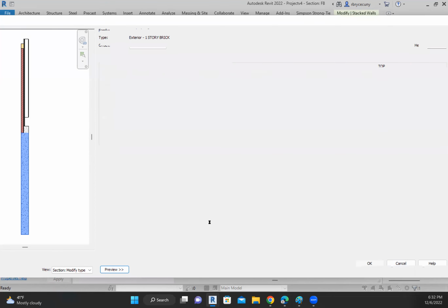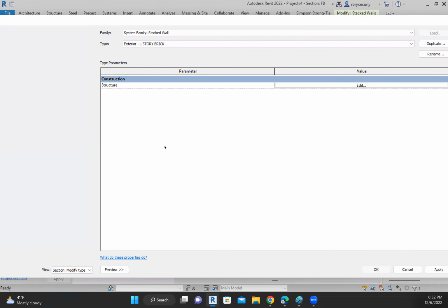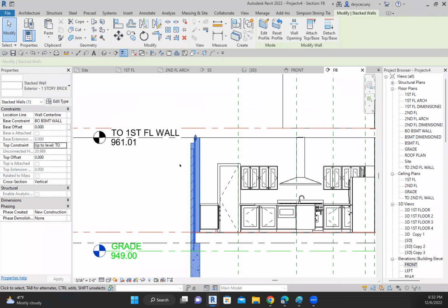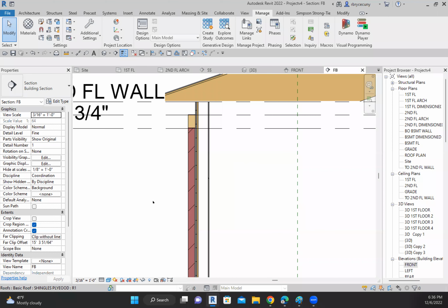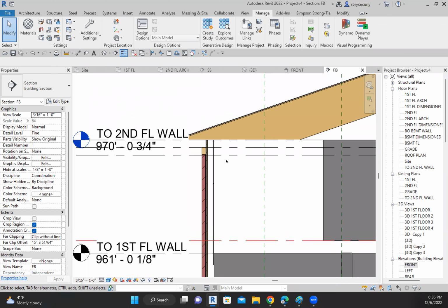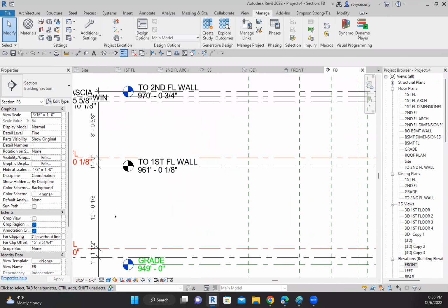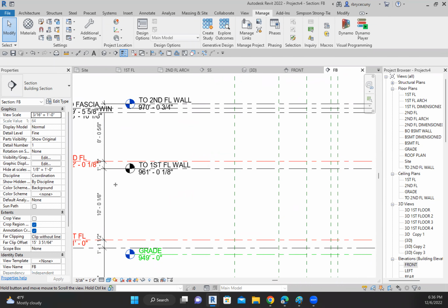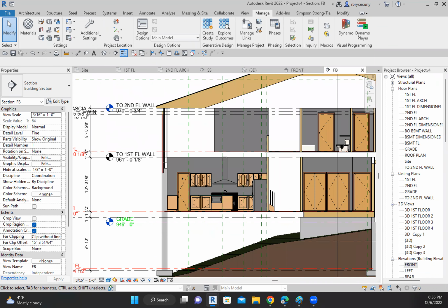So, okay, and okay, everything is good. If this wall goes up, well, first of all, I'm going to pause it for a second and just change the units. Okay, so what I did was I changed my units to feet and inches. That makes more sense to me, and I can set that. And what I'm looking for to happen is that the variable unit, which is the basement wall, stretched in order for all of this to work.